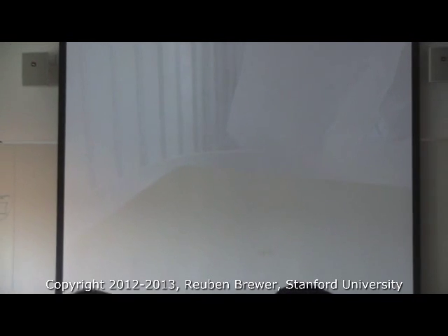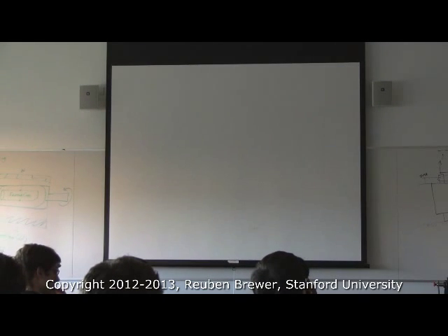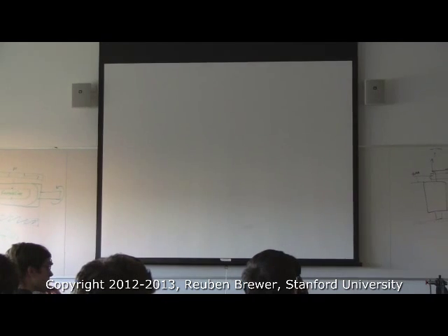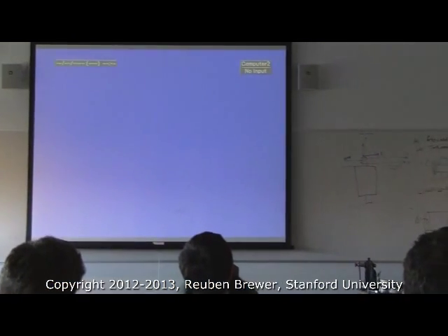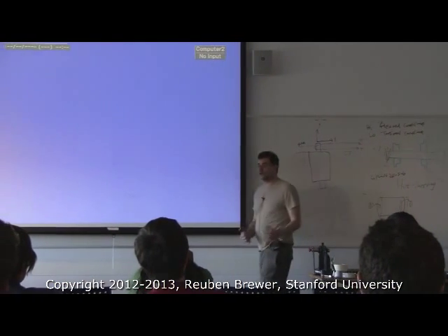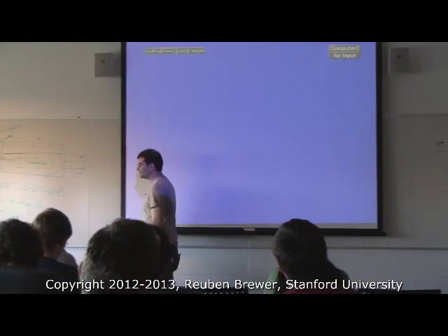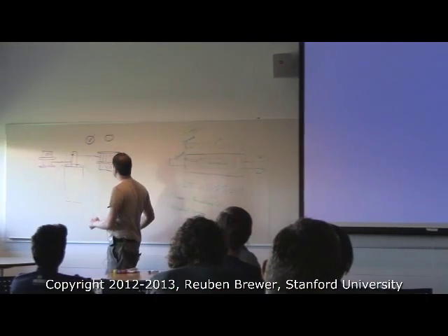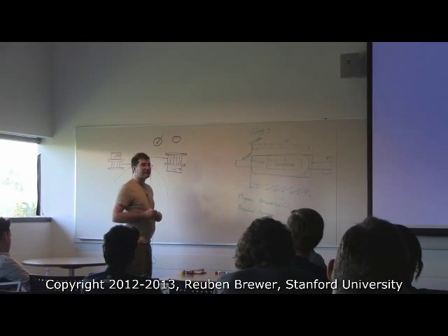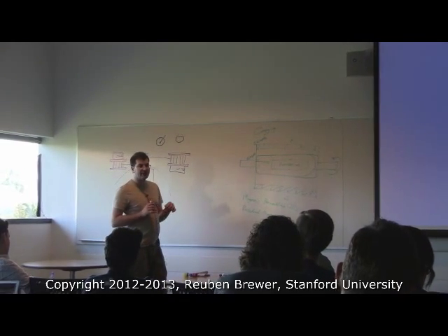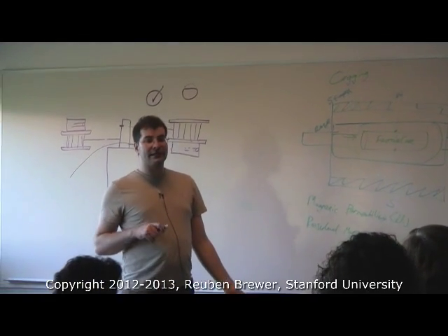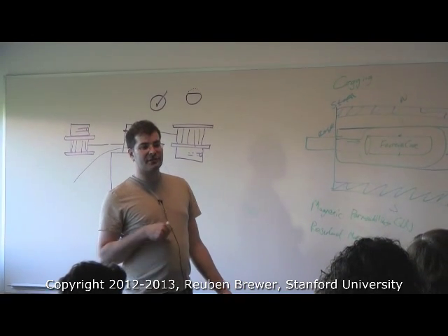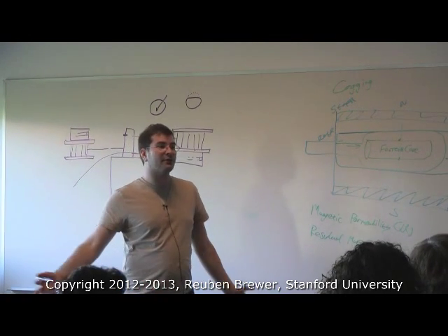What do set screws do? They vibrate loose. Okay. What are set screws supposed to do? Nope. Fundamentally, why are we using any type of clamp or set screw or anything? To transmit torque. Set screws transmit a finite amount of torque. You can't put an M1.6 or M2 set screw and expect to have infinite torque.